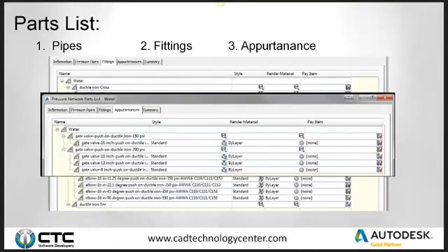Make a parts list that will only have the pertinent valves in there, the pertinent elbows, T's, crossings, and then the pipe sizes. The pipe sizes 6, 8, 10, 12. Those are the common. Yes, you'll get down to 3 and 2 when you get into the residential neighborhoods. But just have a parts list for the sizes that you're going to need.